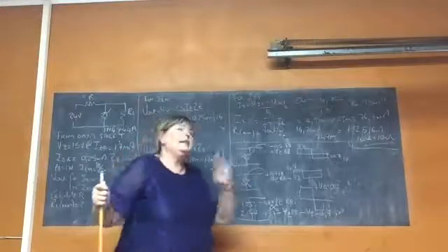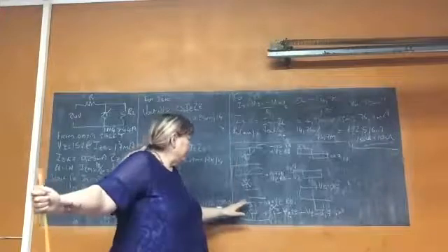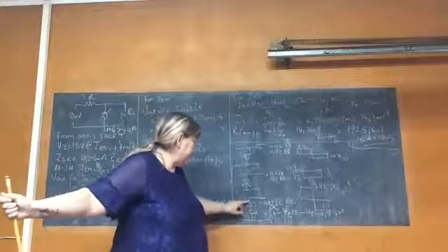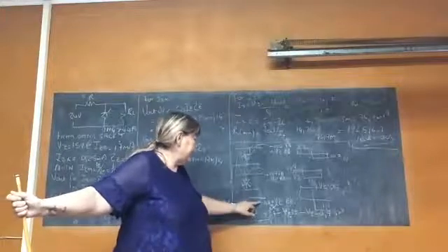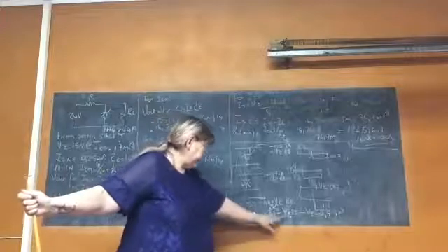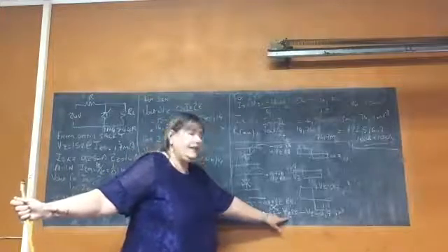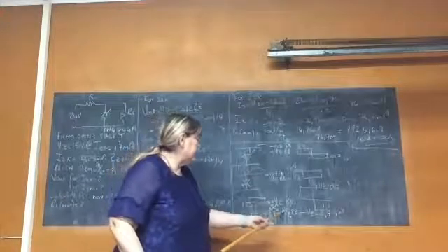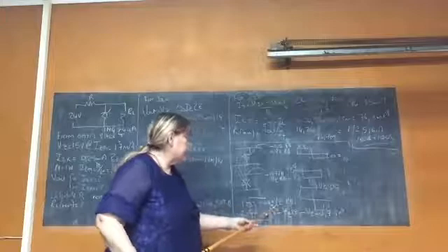Why do I need the two? If the one Zener is forward biased to give me minus 0.7, the other one will be reverse biased to give me minus Vz. And that is why I've got this little cross. This cross to there, that cross to there.